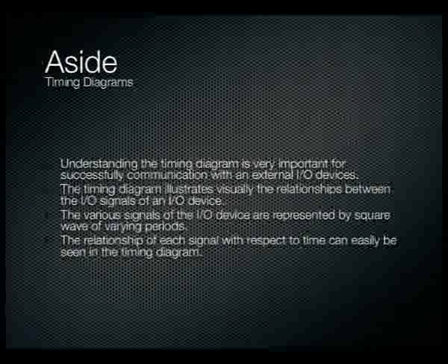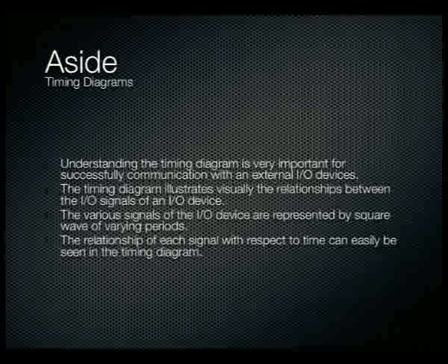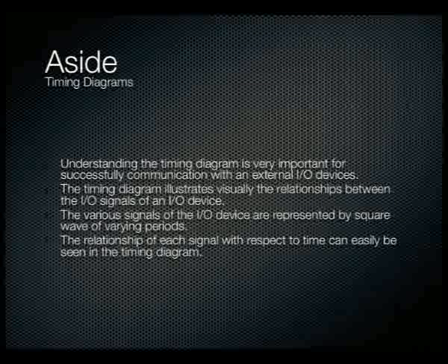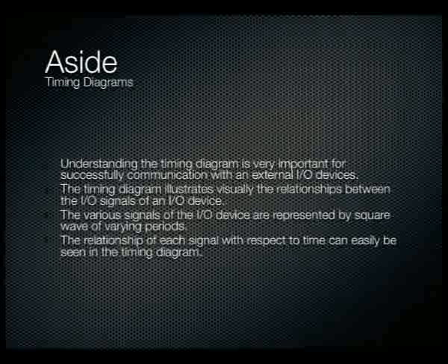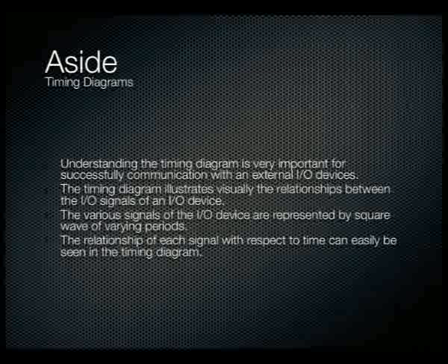But before I do that, I might just reiterate something that you should be familiar with, which is timing diagrams. Timing diagrams are very, very useful for understanding how you need to communicate with devices. If you're going to do some sort of synchronization in software to talk to a particular device, you've really got to understand its timing diagram.